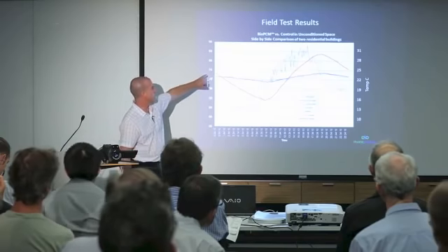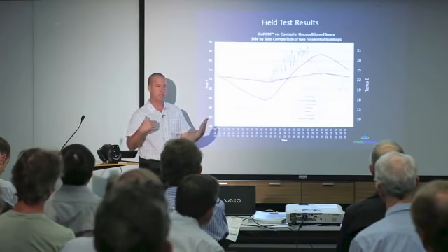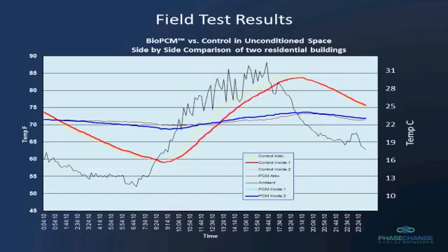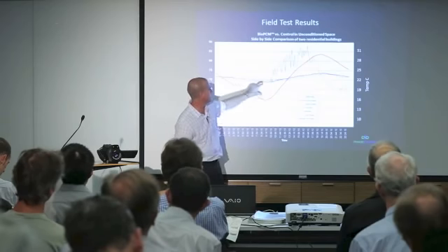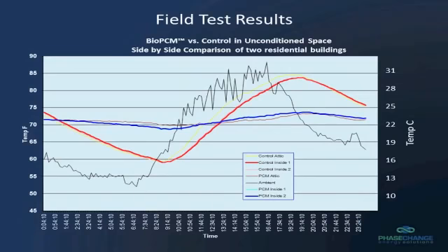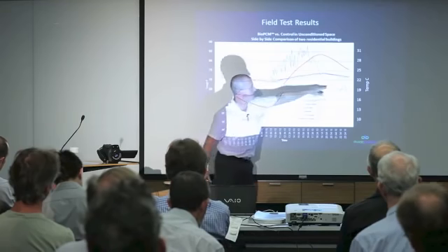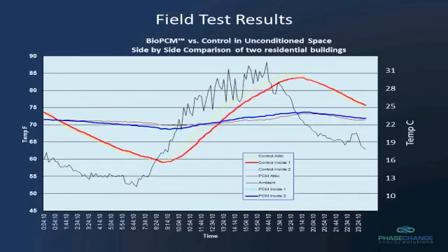With an insulated home, the house lags behind the outdoor temperature because insulation just slows the transfer of heat down. So the heat transfers through, the house eventually gets cold, you've got to put a heater on through here, and then you get to here again and it gets too hot and you've got to put an aircon on through there, or you just put up with it, which is probably what some people do. With phase change material, here we're releasing heat, which is keeping you warm. So we're not getting below 21 degrees or so. And then here we're absorbing heat, keeping you cool.